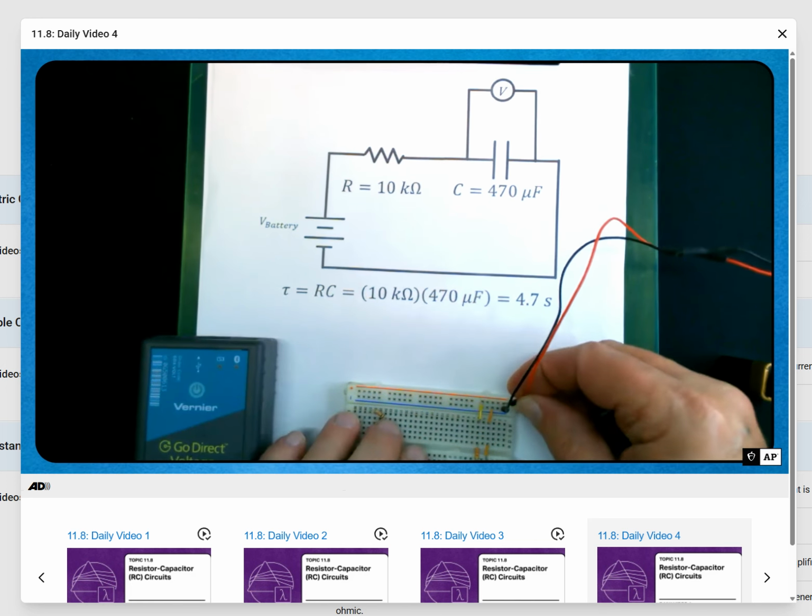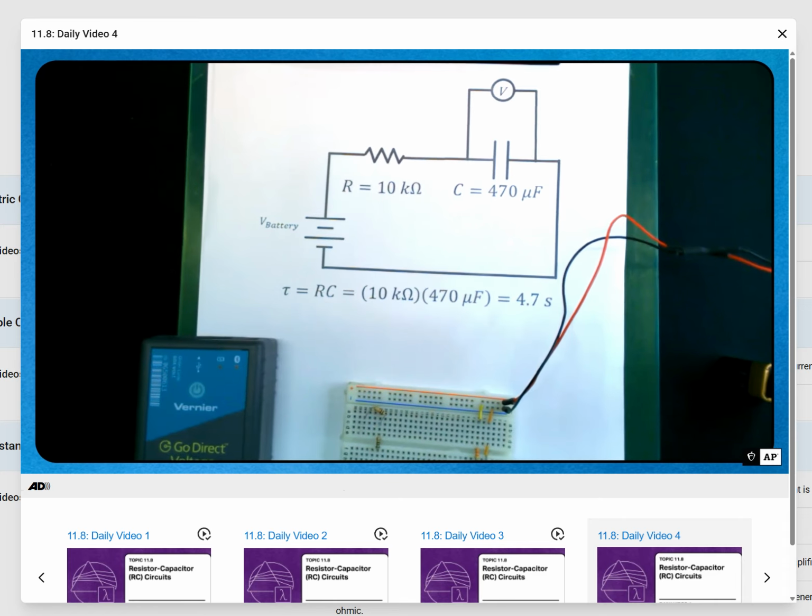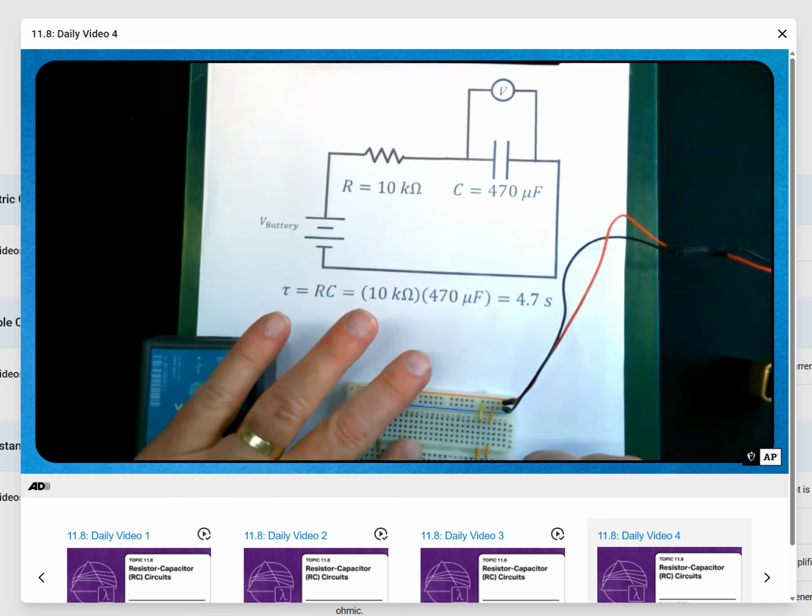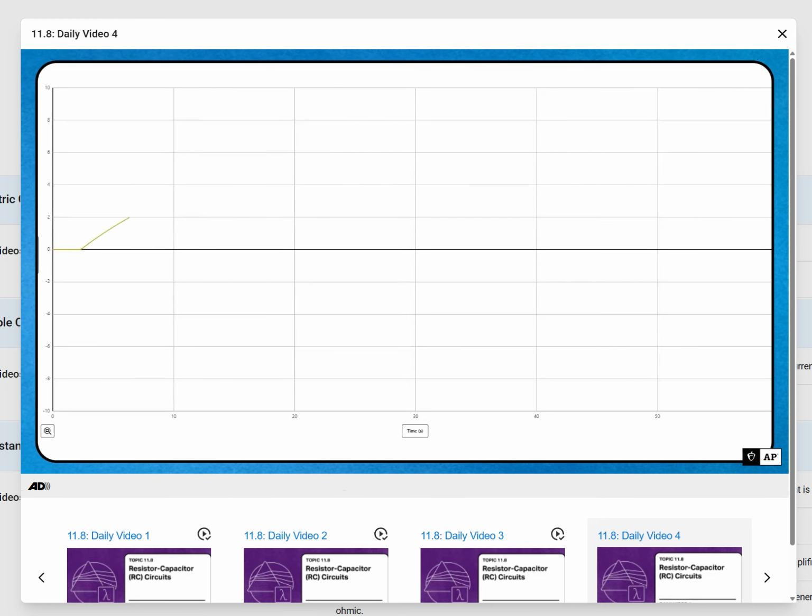Let me hook up power, remove my jumper wire. I'm going to collect some data. Okay, you can see that curve is much more shallow. It's still exponential, but it's going to take a much, much longer period of time to asymptotically approach 9 volts. The time constant for this one is 15.7 seconds. So hope that connects all those dots for you. Anytime you see a little LED flashing on and off, somewhere inside that gizmo is a capacitor charging and discharging just like this one is doing.